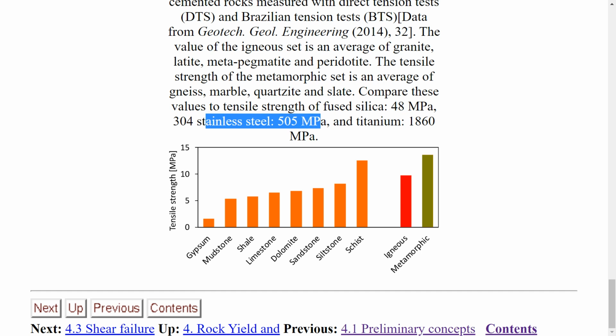What would be the tensile strength of an unconsolidated sand or an uncemented sand? Zero, no strength at all. And we do find those materials in many of our applications. So many of those materials also are going to have a tensile strength which is equal to 0. They always have to be in compression. If they are not in compression, they can fail.